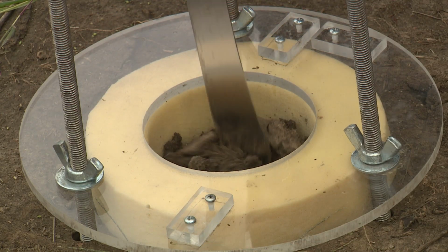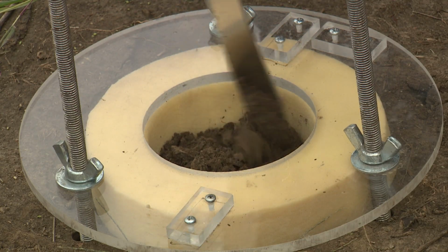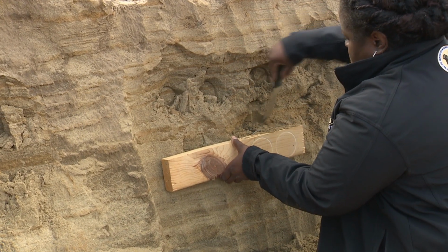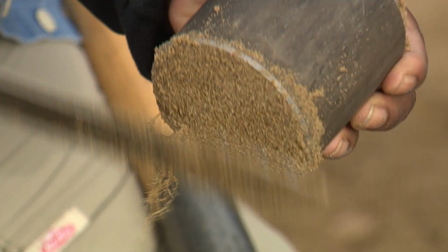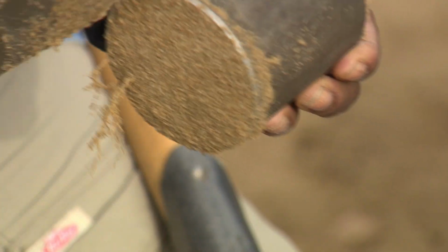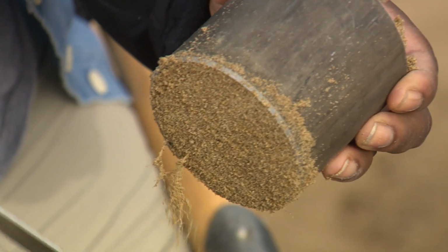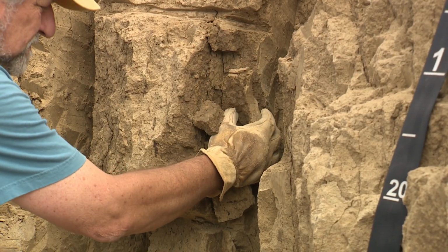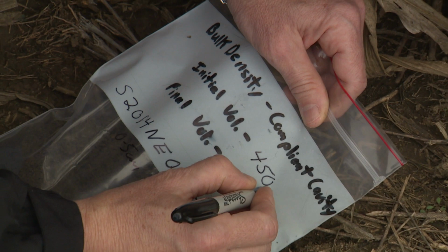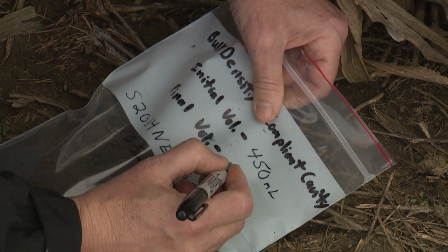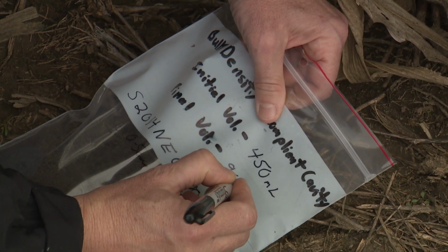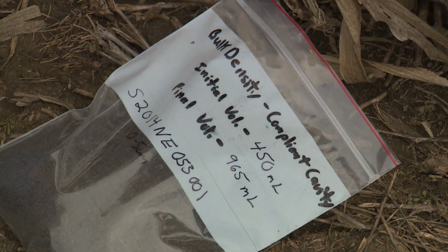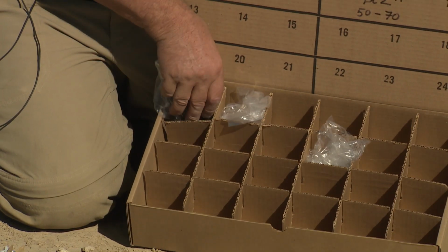Soil bulk density is the ratio of mass of solids to the bulk volume and is used to convert data from a weight to a volume basis. The value is essential for many soil data calculations. Because of this, it is essential to collect a quality sample of the proper size prior to submitting it to your lab. It is also essential to label the sample completely with a proper sample number and layer depth. Some sampling methods also require recording the volume of each sample.